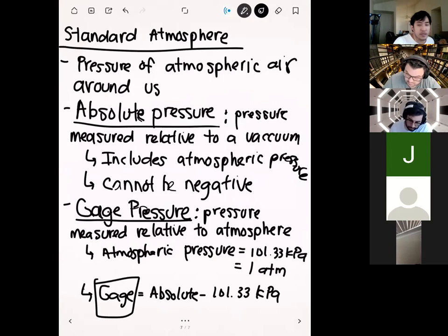Because remember what we said was, the pressure at the free surface, or anywhere that we have that little triangle, is equal to 0 pressure. Okay. And so that zero pressure, it's not absolute pressure, because the top of the water in this glass is not at zero pressure, it's at atmospheric pressure. But just for calculation purposes, we assume that we're using the gauge pressure so that we can use zero pressure for anything that's at atmospheric. Okay.